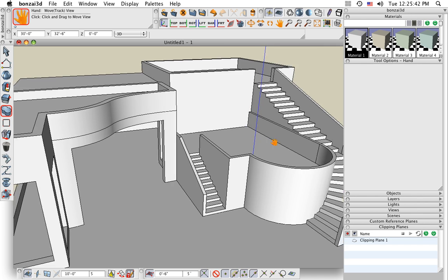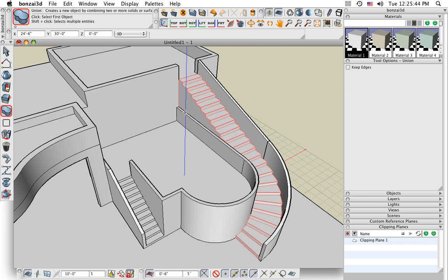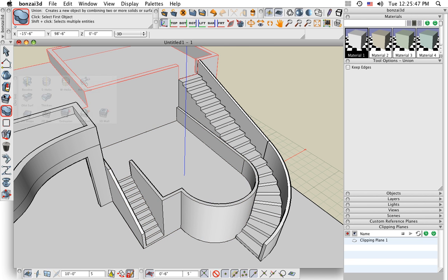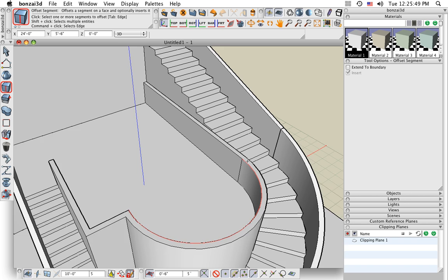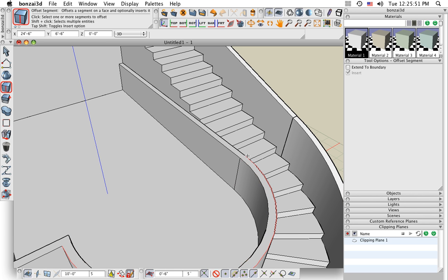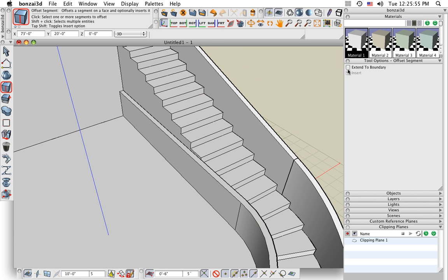Great. One more step left to do is to slope also this part of the wall here. We first break that top face. I need to have a segment right here. This is where the wall will bend, so we'll use the offsetting to do that.